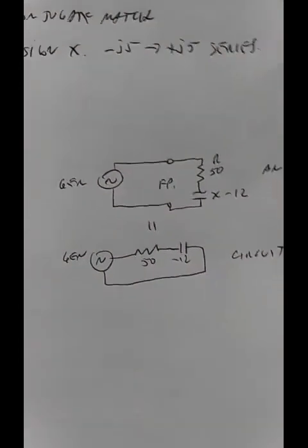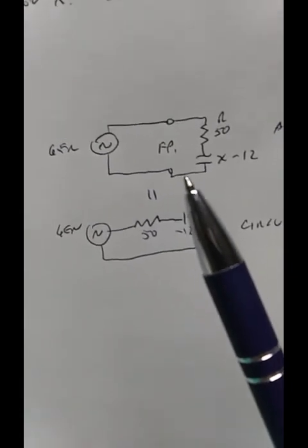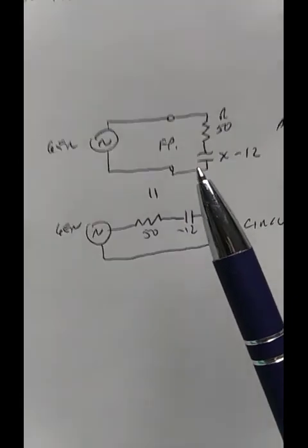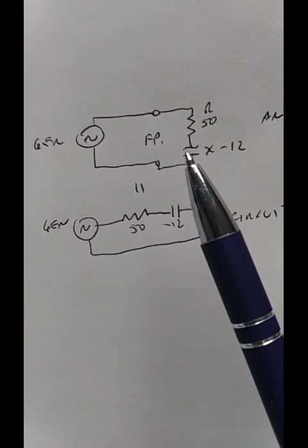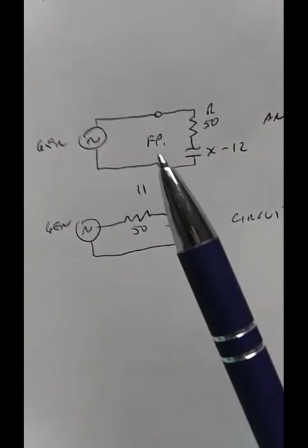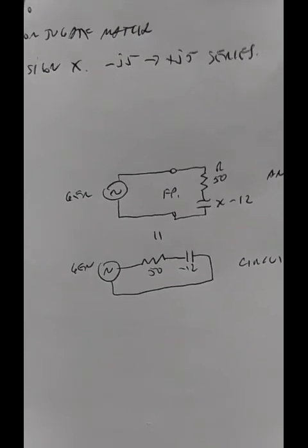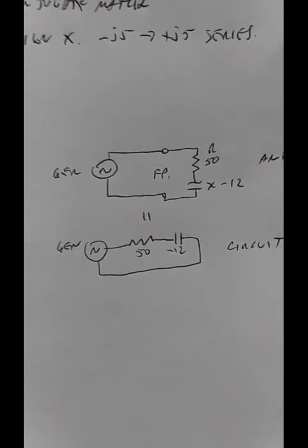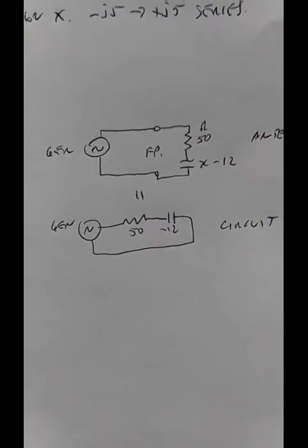Unless maybe, except maybe in the case that putting something at the feed point of a VHF or UHF antenna affects the field associated with this. And at VHF, a little capacitance, a little admittance at the feed point will thoroughly screw an antenna up, and it can't be fixed. For example, put up a VHF or UHF antenna and bring a piece of wood near the feed point. Watch what happens. It'll send a match right down you know where, because wood has an extremely high dielectric constant and is absorptive.